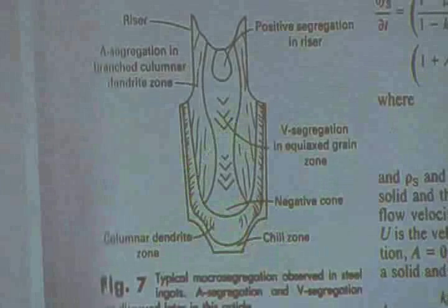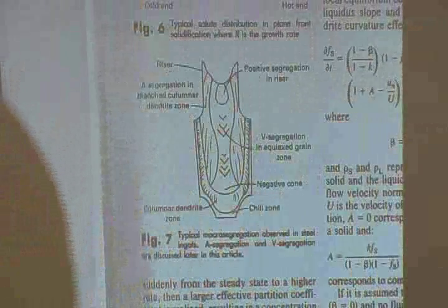So you really have some sort of composite from the original casting. And that's a problem in a lot of cases. You want to break that down, and so you may later forge the product to get rid of it. If you're lucky, if it's iron or titanium, those alloys will actually go through a crystallographic phase change at intermediate temperatures.